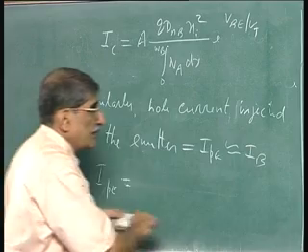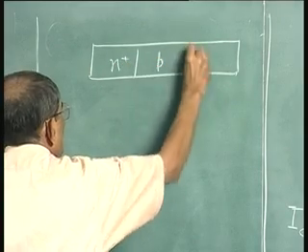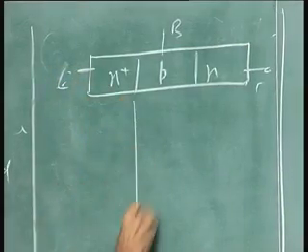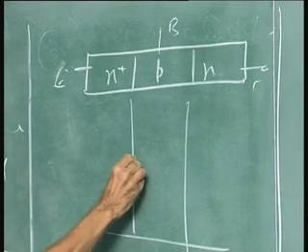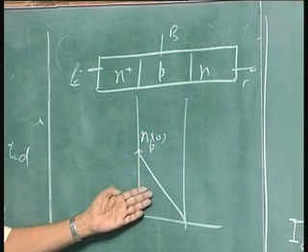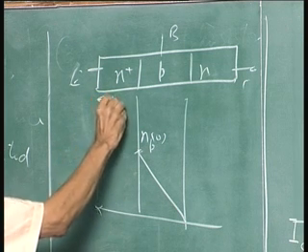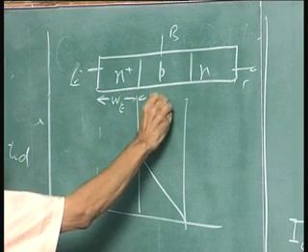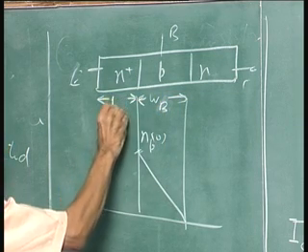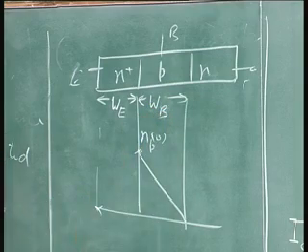Let me put this across to you by drawing a diagram here. N plus, P, n minus: collector, base, emitter. That is the carrier distribution here, NP0, and everything was related to NP0 divided by WB. And here I will take this width WE, small. I think that may not be visible properly for you, WE, and this is WB. So, this current component we have written now.